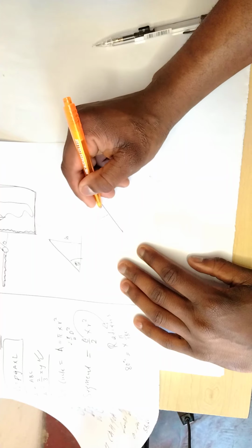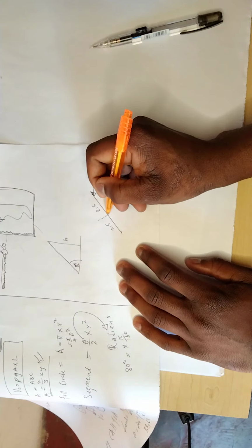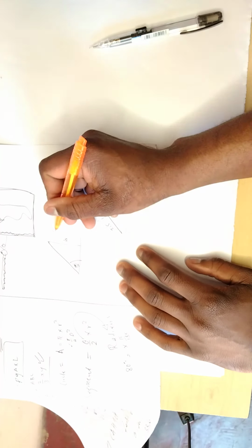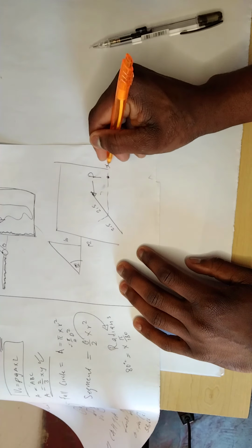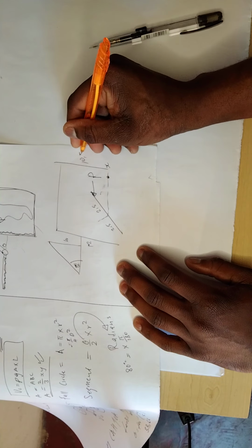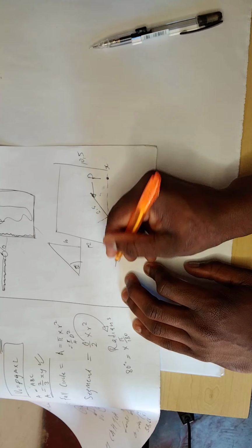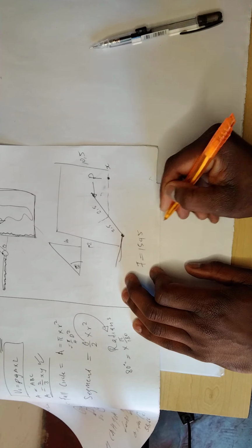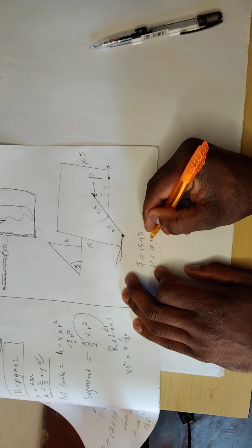And we said that this is going to be 2.5, it's the half. Then this is going to give us a centroid, which is x. We got it as 10.5, I don't remember exactly. Then this is where our hinge is. We found the force, which is 1545, and we found the height, which is 10.48.